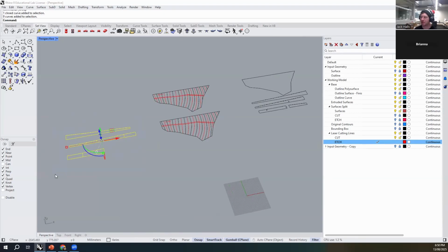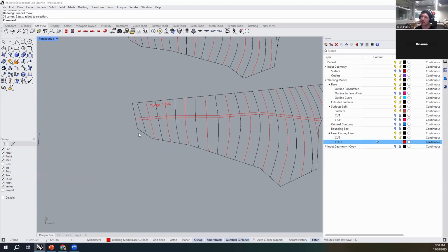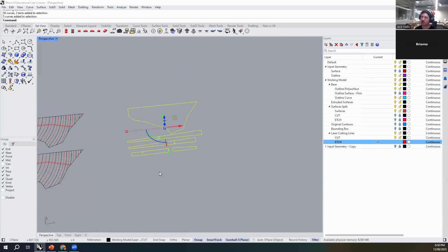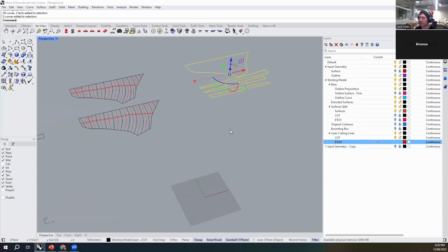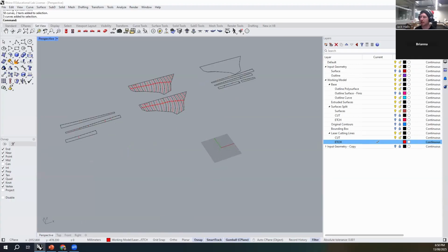We've got our optics card, which is our thin edge that is, in my case, a black thin card. We've got our top surface contour pieces, which will be laser cut and then stacked, which is 1.8mm box board. And then we've got our structural component, which for my design is 3mm box board. So three different materials that we're going to lay out in our laser file.